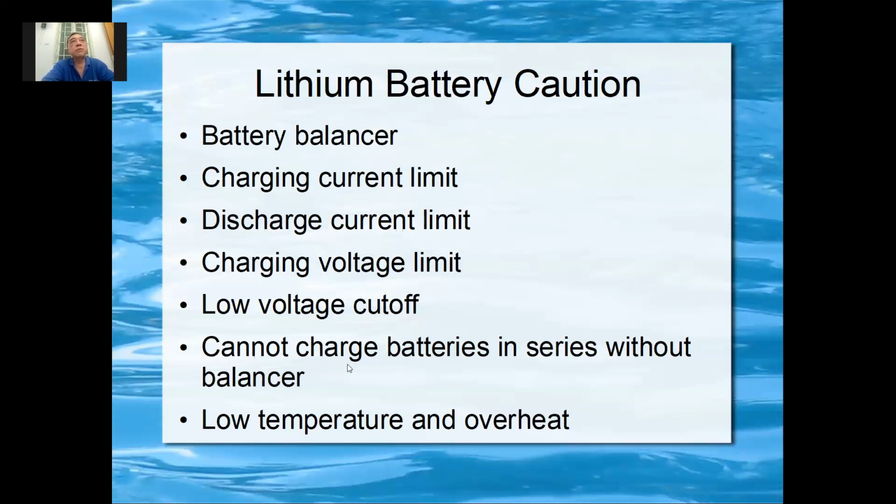Okay, so you don't charge the battery in series without a balancer. This one I explained earlier already. This means if you have individual batteries, let's say you get 4 lithium batteries to form a 12 volt, you cannot put 4 batteries in series to get 12 volt. You must add a balancer that balances the 4 batteries together to get 12 volt. And the balancer for lithium ion and lithium iron phosphate are different. So when you want to buy, make sure you buy the correct balancer for the right battery.